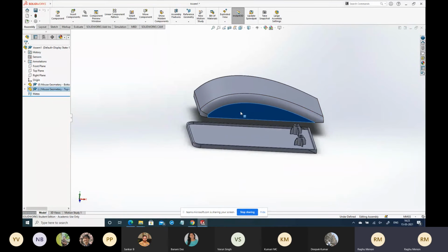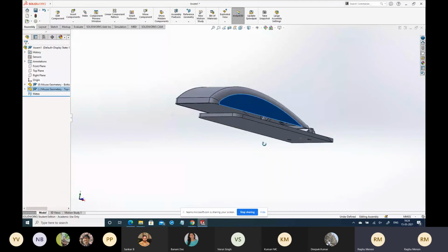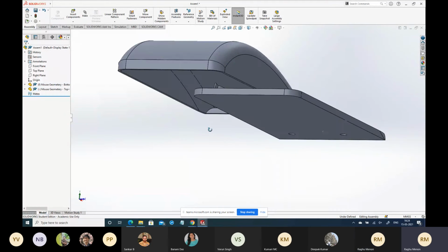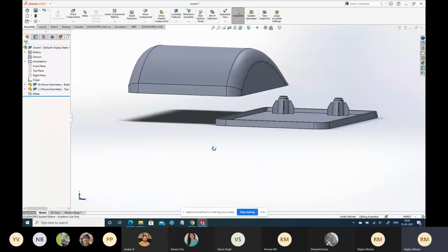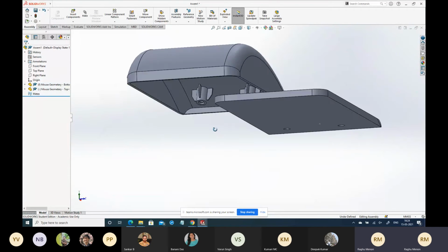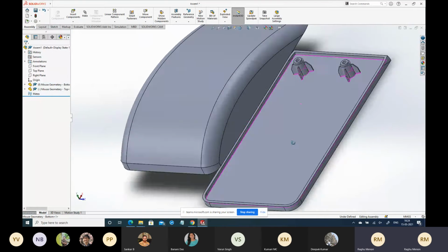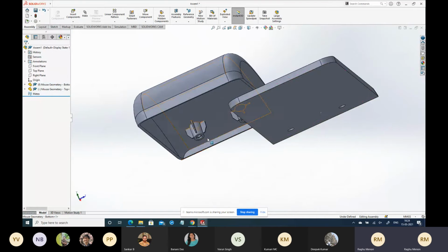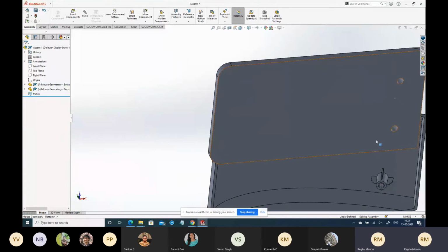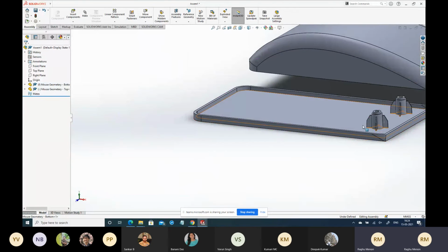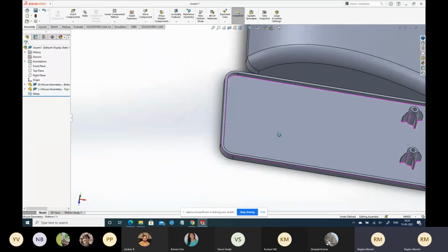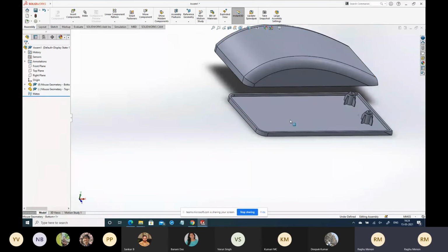Now, I want to create a joint, right? So I have to mate these parts. Usually you'll take great care to make sure that this boss and this boss align and fit into each other, so we can put a screw through this, and all those kinds of things. So you'll have to add all those details. This is not done over here.